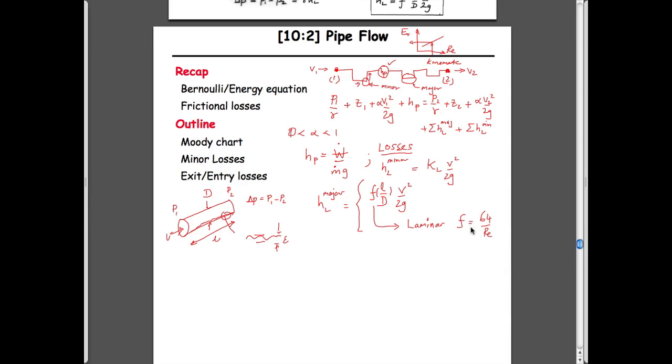So it's always this magnitude for a circular section pipe. When it's laminar flow, where roughness doesn't come into account, it's always equal to this magnitude. And if it's turbulent flow, then the friction factor is a function of Reynolds number and relative roughness, roughness over diameter, because that's the characteristic.